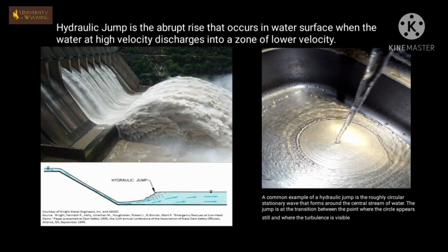A major part of the job of a civil engineer working in the field of hydraulics is designing against erosion from the flow of water. When we try to control the flow of water, it often leads to the potential of having fast moving erosive conditions. Like when we make releases from a reservoir behind a dam into a spillway, the water will come down at very high velocities. This supercritical flow can cause erosion and eventually lead to failure of the structure.